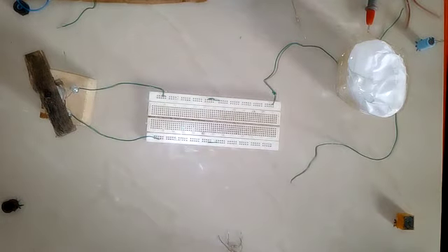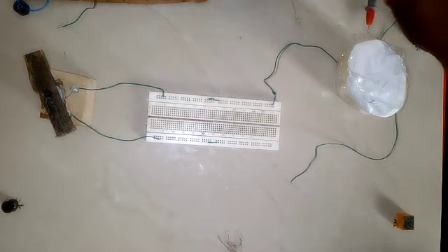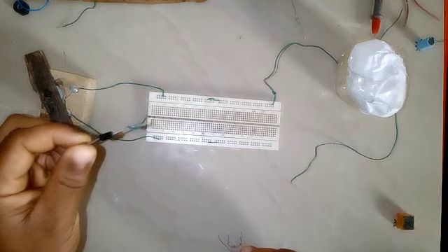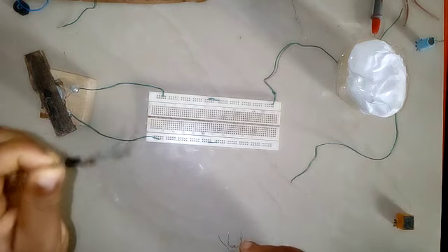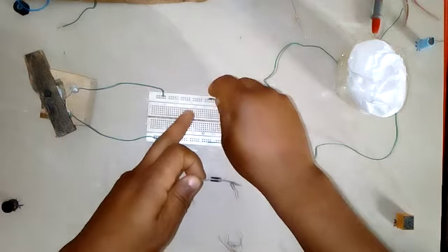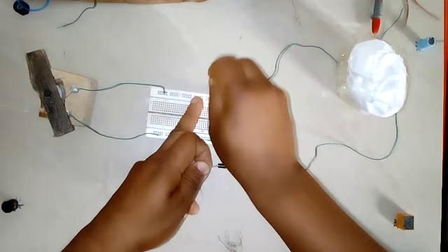So assume for a moment that I want to program this DC motor to turn in only one direction, so that if somebody by error swaps the terminals, the motor will not turn. We want it to turn in only one direction. We could employ the services of this diode. I want to put it here. So I'll take the jumper out.